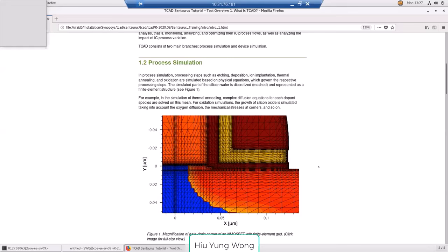All the transistors from fabrication, how do you make a transistor? Like what Tuyen said, she went to David Parent's lab. You do implantation, you do annealing. Those are all physics behind. Physics tells you under what temperature how the silicon will diffuse, and under what energy the ion will penetrate into the wafer. And then you form something called a junction.